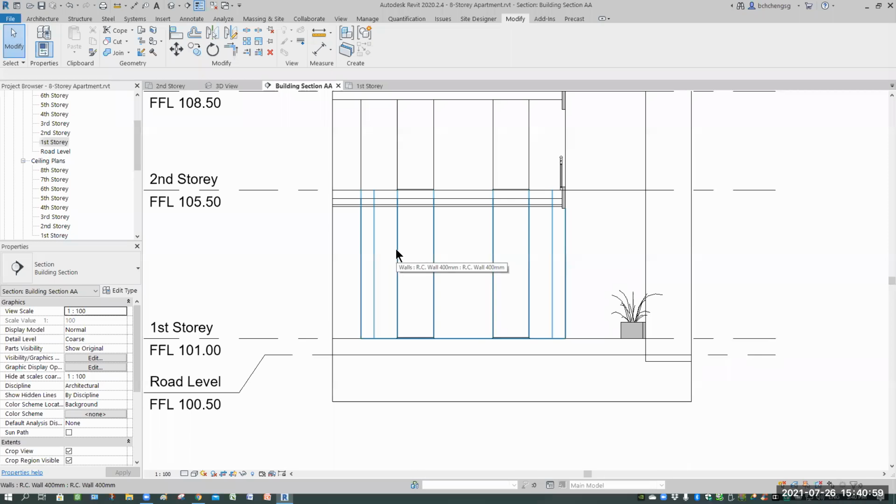For the car lift door, normally it is higher than the standard one. Standard is around 2 meters to 2.1. That is the clear. Then plus the structure another 100, so it's around 2.2. So for this special case, first story, I'll give this, let's say maybe 2.6 and see how it looks like.